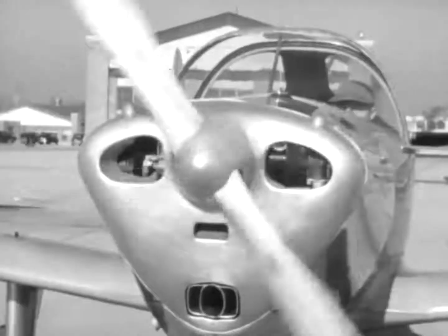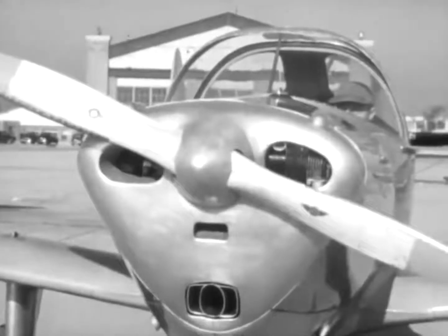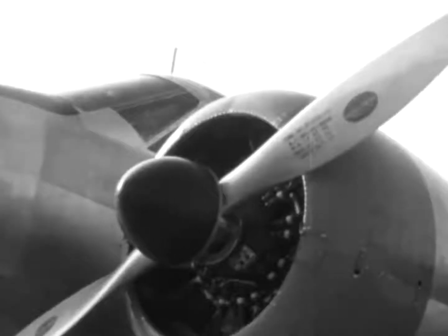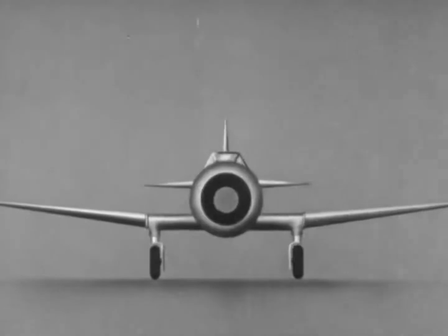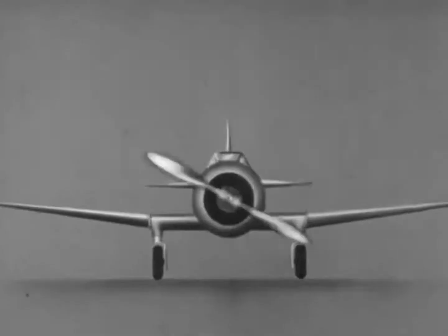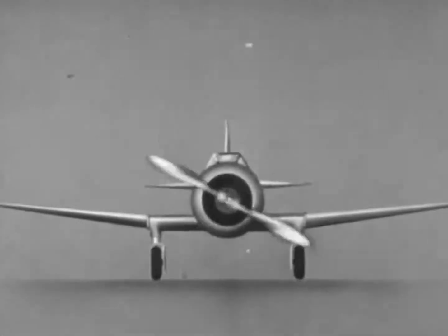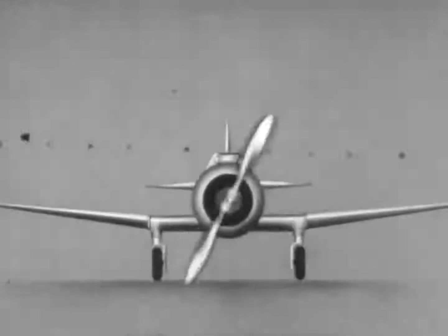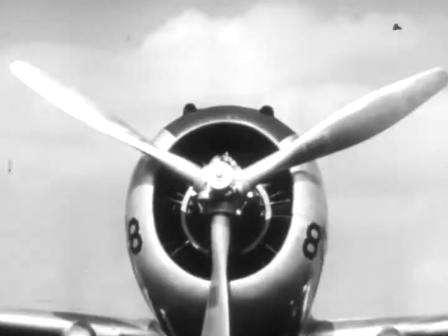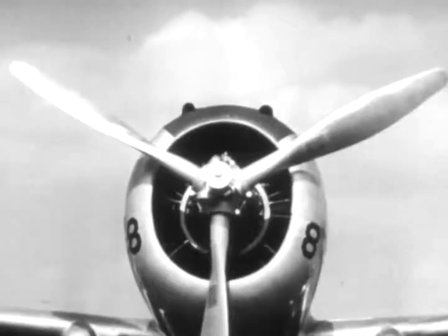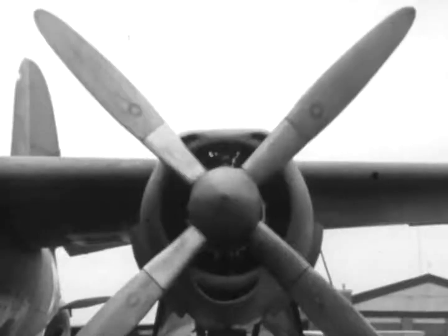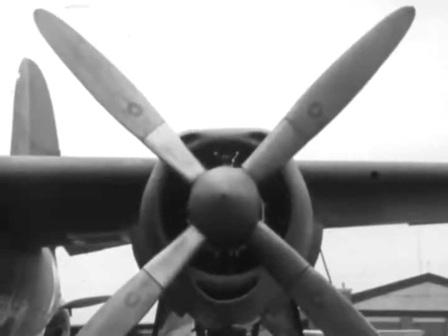This relatively small engine can turn a small propeller. This larger engine needs a larger propeller to absorb its greater power. If still more powerful engines were equipped with two-bladed propellers, they would be so large that the blades would touch the ground or else require a landing gear of excessive height. Therefore, three-bladed propellers are coupled to medium-high horsepower engines, while four-bladed propellers are usually found on superpower engines, about 2,000 horsepower.